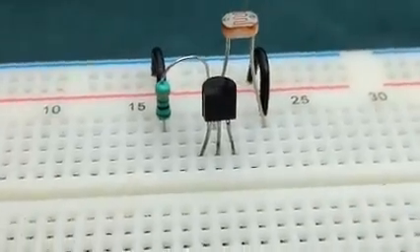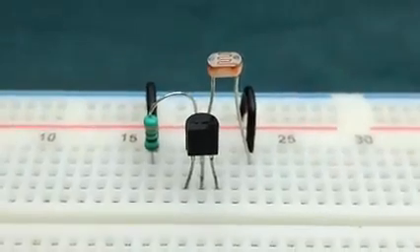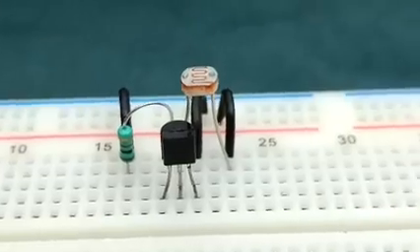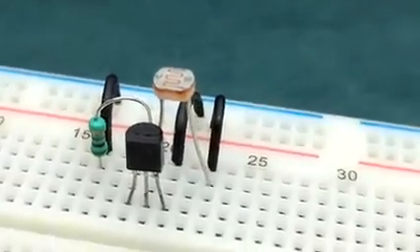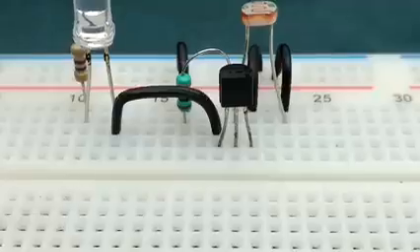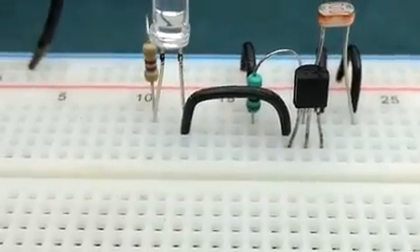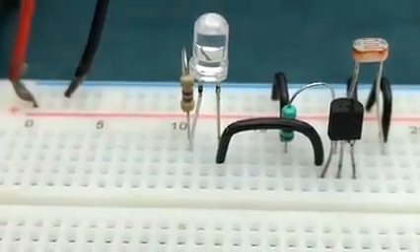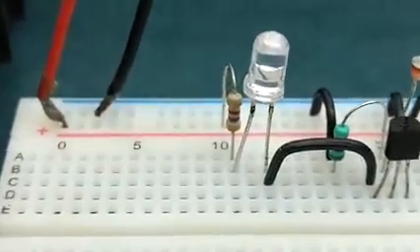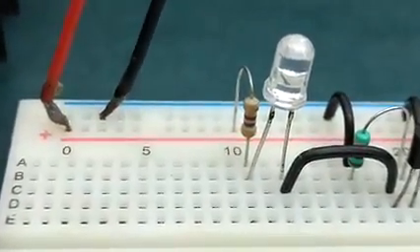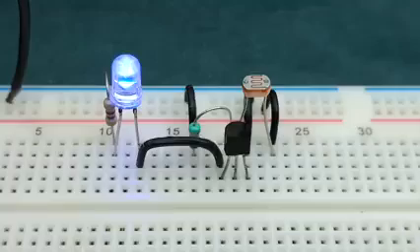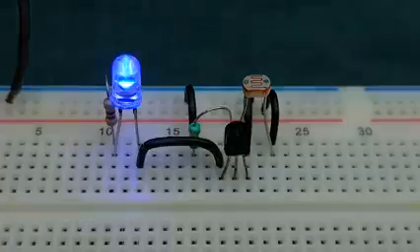Emitter, which is at pin 3, is of N junction and has to be in forward bias. So connect pin 3 to negative rail. The collector is to be connected to the load. So connect pin 1 to negative terminal of the LED, and positive of the LED is connected to positive rail via a 470 ohm resistor. Turn on the power supply, anything up to 12 volts, and here you go, the light sensor circuit.